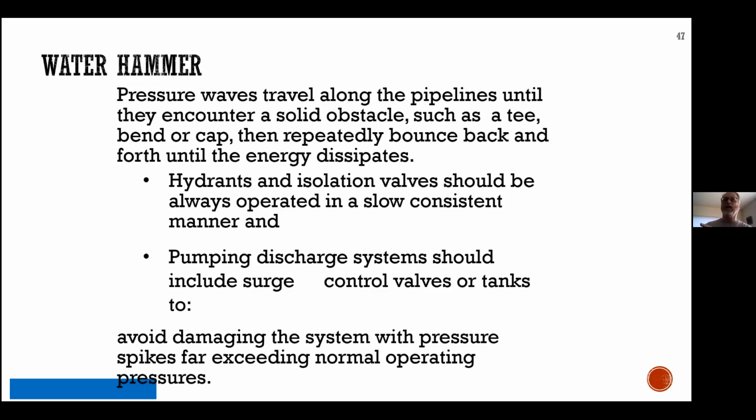So you may not want to take 8 minutes to shut it down, but you do have to shut it down slowly. Otherwise, and you can hear it as you're shutting down a bad water main break, you will hear that velocity as you're slowly closing off the flow. All that energy is building up on the upstream side of the valve, and the whole ground will shake.